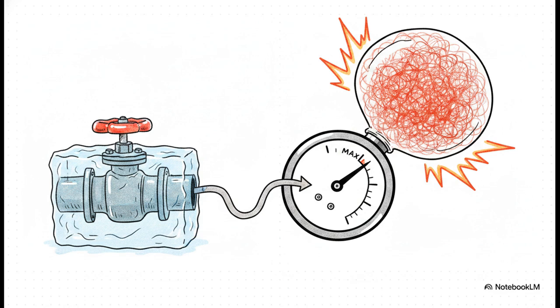It introduces something incredibly dangerous called integral windup. Imagine a huge disruption, like a frozen water valve. The integral term doesn't know the valve is physically stuck, right?